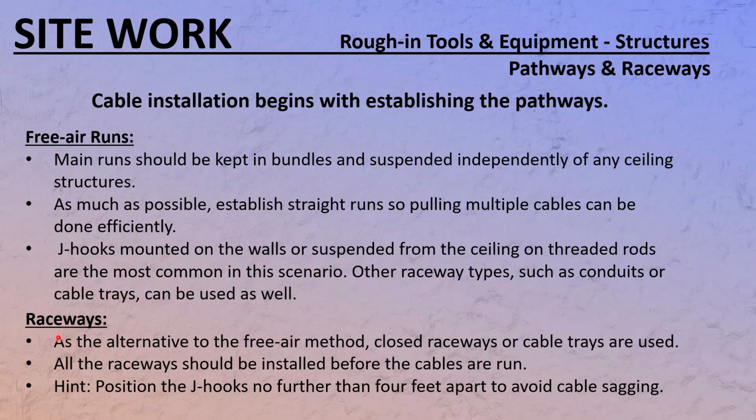Raceways. As the alternative to the free air method, closed raceways or cable trays are used. All the raceways should be installed before the cables are run. That's a stage of the job. You complete that stage, you move on to the next one. Mount the raceways first, then pull the wires. Don't just do 30 feet of raceway, pull the wire, and do another 30 feet of raceway and pull it. No.